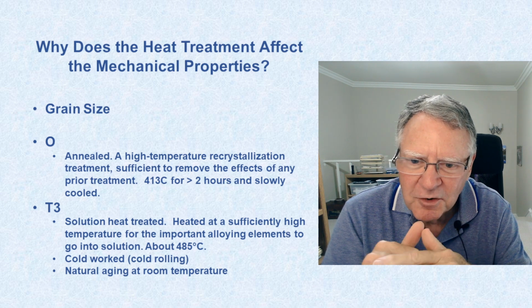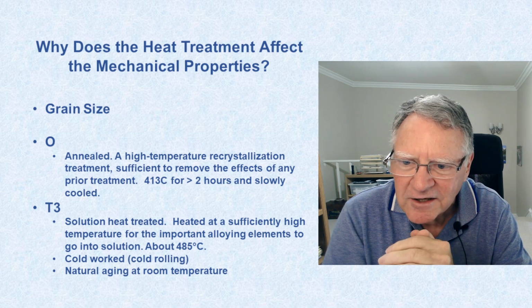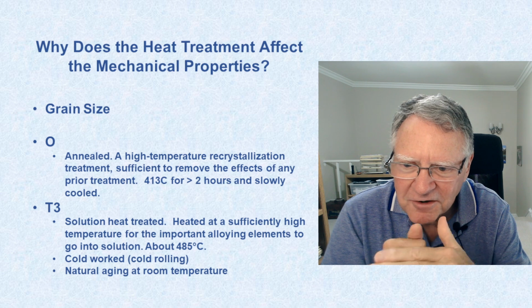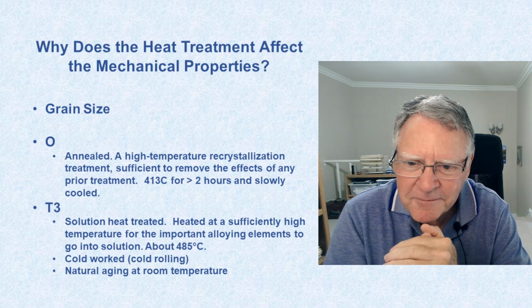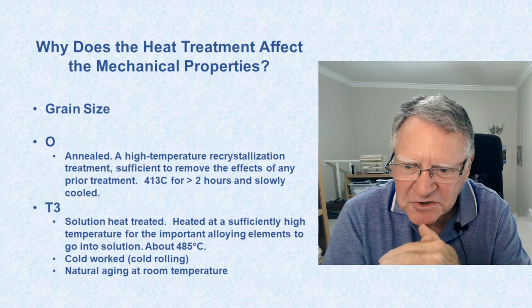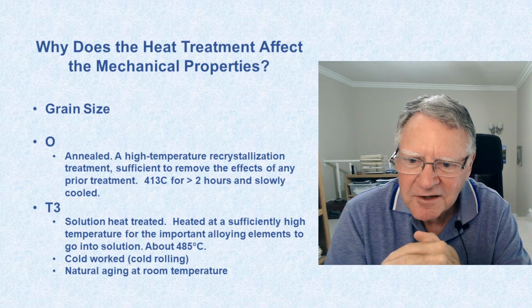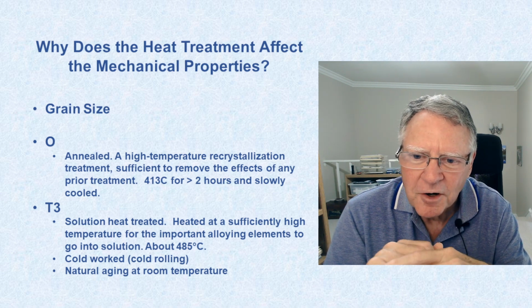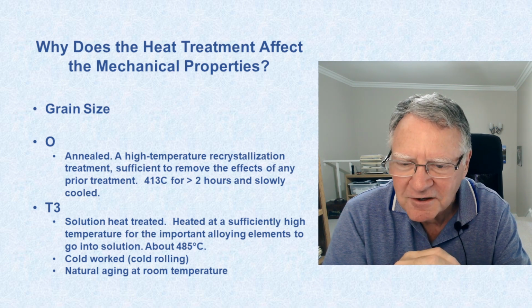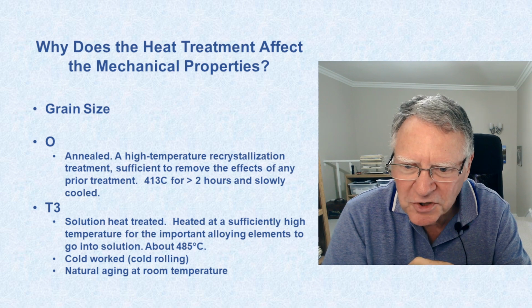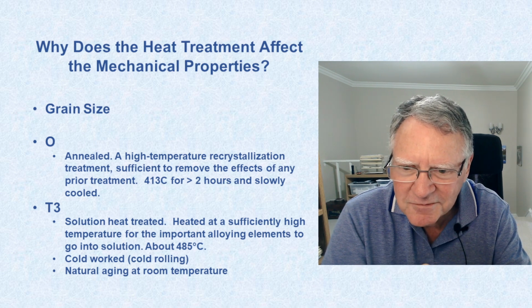Say you bend the aluminum and it starts to slip. You start to form a slip line or a slip dislocation. And there are preferred weaker planes in an aluminum crystal. I think typically the 100 plane is a weaker plane.